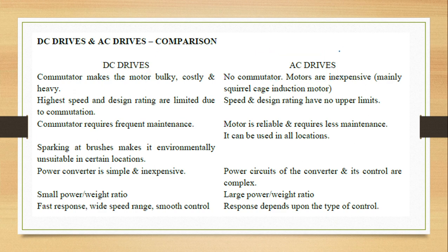Now, in AC drives further, there are more subdivisions. You have induction motors, synchronous motors, brushless DC motors, stepper motors, switched reluctance motors, and all of these you have already studied in the synchronous and induction machine subjects. Just to refresh what you have studied, permanent magnet synchronous motors and wound field motors have good efficiency, but the cost and size are high. Permanent magnet motors have high efficiency and power factor compared to induction motors, but the maintenance and the size are high for the same rating of the induction motors.